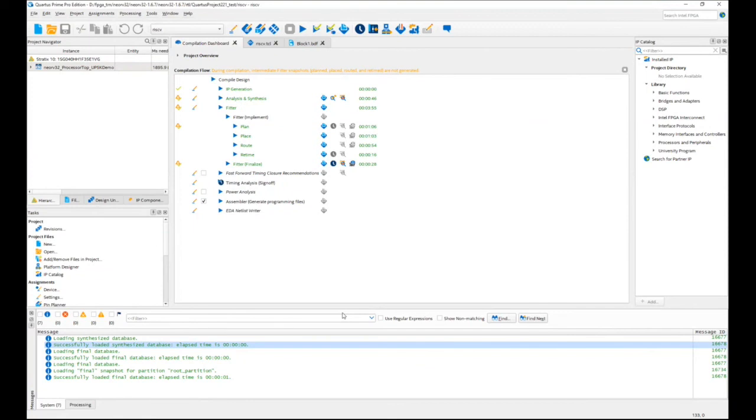You have a two register design. Not only do you have all those register places, now you've got all those register places minus one, and the tool's got to figure out where to place those. And again, you're going to tell me, well, Steve, it's a two register design, the solution is trivial. It is. But now you have a bona fide design out there, and the tools need to figure out how to place and route that. It is kind of a long-winded answer, but I feel a little bit of this background is necessary. It's got to figure it out somehow, and so it can't exhaustively try every scenario.